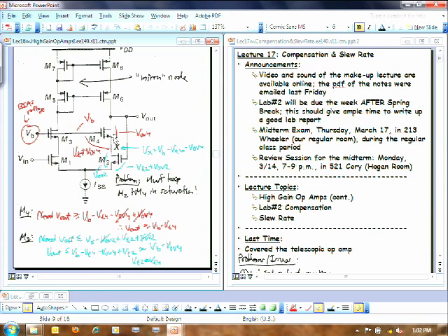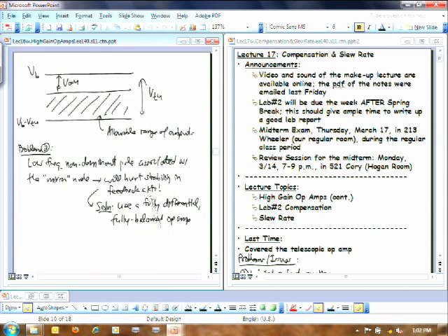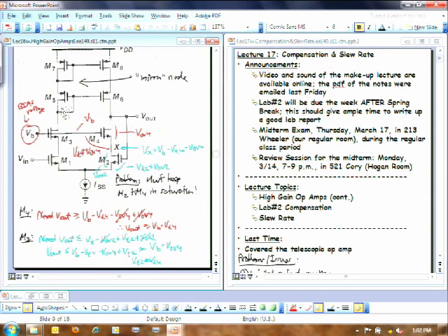We said the solution to a lot of these problems is to not do mirroring, but actually do what's called a folded cascode type op-amp. That actually separates this thing from the rest of this. I guess you could still do mirroring on that, but it separates this from this, which allows you to drop less voltage across. Well, it opens up more voltage here for you to swing.